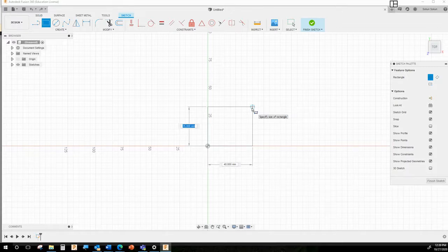And don't worry if it looks exactly like mine, just make sure you've got a rectangle drawn. So again, all I did was click and hold down my mouse button and drag until I see a rectangle. And then what I'm going to do, and you might have the x-axis highlighted instead of my y, but whichever one's highlighted, just type in 100 and then hit tab. Don't hit enter yet. Hit tab to get you to the other one. If you try to move your mouse to the other one, it's going to freak out the rectangle. So hit tab and type in 100.